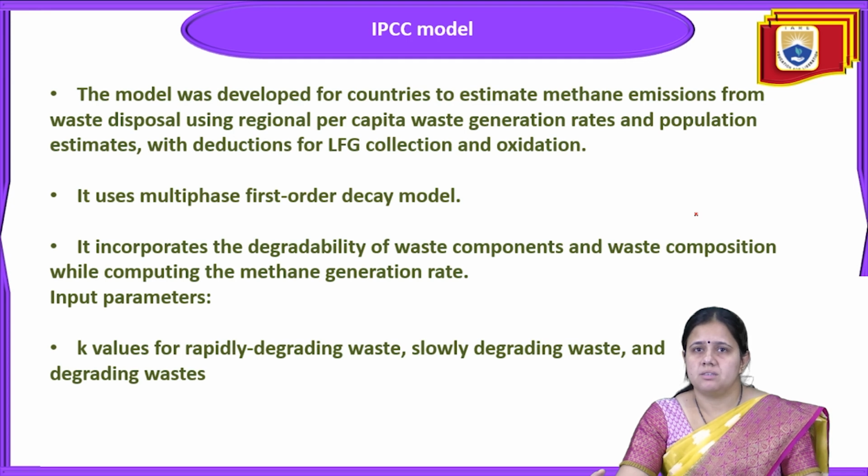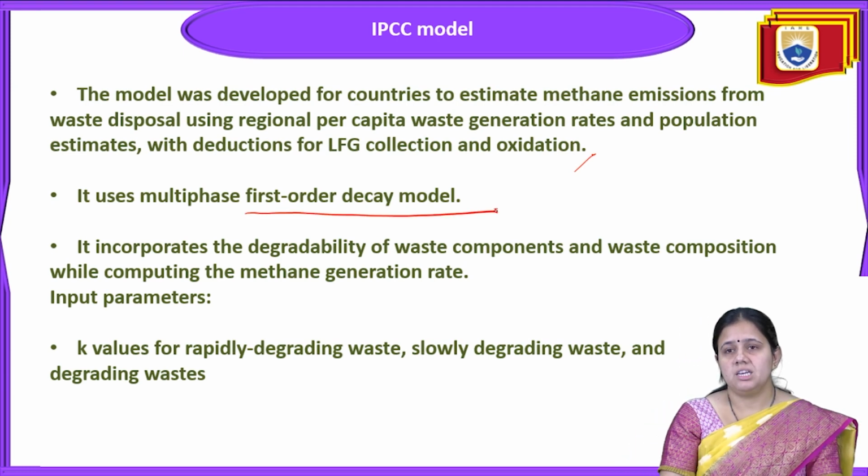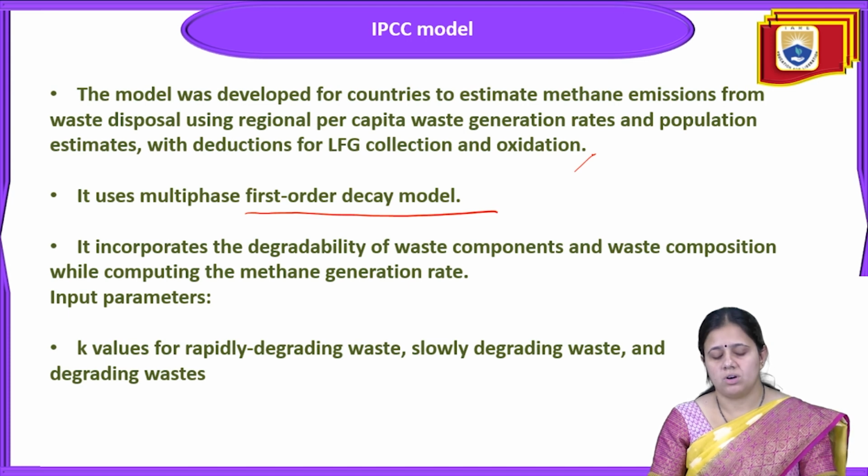The next model is the IPCC model. This model was developed for countries to estimate methane emission from waste disposal using regional per capita waste generation rates and population estimates, with deduction for landfill gas collection and oxidation. It basically uses a multi-phase first order decay model.